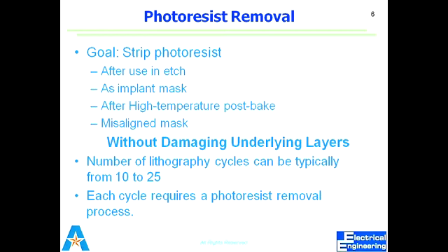In lift off, maybe photoresist was deposited. It actually helps you pattern any thin layer, right? If you want to pattern a thin layer, you will have to do photolithography and then you go for the etching process. So by using photolithography, the exposed area would be etched away and the area that is protected by the photoresist would not be etched. So any thin layer can be patterned by using photolithography plus etching. At the same time, the same patterning can be done the other way, that is named lift off.